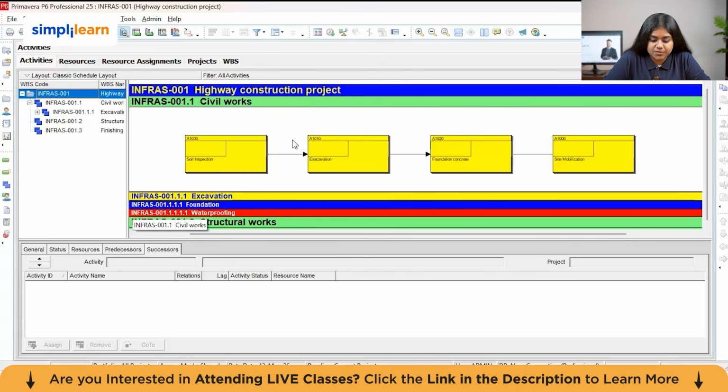So basically the difference between the late and early dates gives us the float. The total float is how much an activity can be delayed without pushing the project end date. An activity with 20 days of total float can start up to 20 days late and the project will still finish on time. Free float is how much an activity can be delayed without delaying its immediate successor. So activities with 0 total float are on the critical path. If we have delay in any of these, then the finish date moves. These are the highest priority activities to monitor.